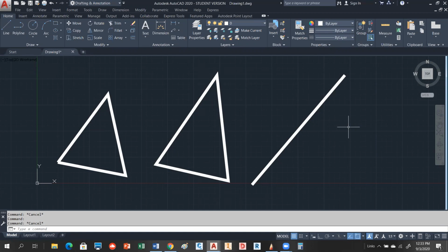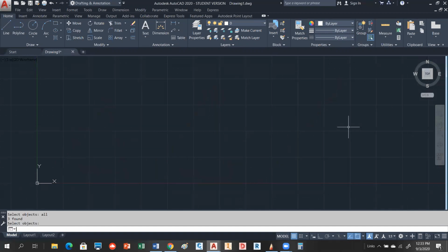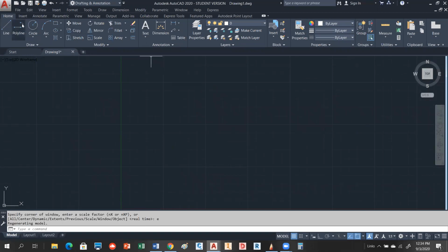Okay. All right. So if you would, go ahead and delete your objects that are on there for me. I'm just going to hit erase all and enter twice, and that'll take it out. So we also have an arc object that we can attach to this. So let's go to the polyline command, pick a point, and notice then once you pick a first point, there's an arc option that pops up. So you really have, in the polyline command, you have what's called a polyline and a polyarc, okay? You always start out in the polyline option.